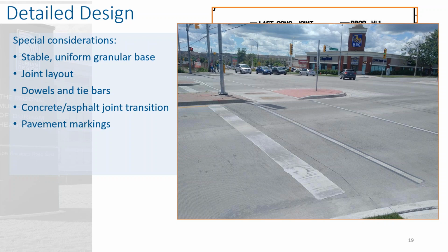So it's just a thicker black mark below the white normal crosswalk line. The other thing that was new to us for pavement markings was that we usually use thermoplastic or field reacted polymeric pavement markings. And thermoplastic really relies on the thermal bond between the paint and the pavement surface, which works well for asphalt, but not so well on concrete. It's a bit more porous and it doesn't get that bond. So MTO actually recommends that you don't use thermoplastic on concrete pavements.